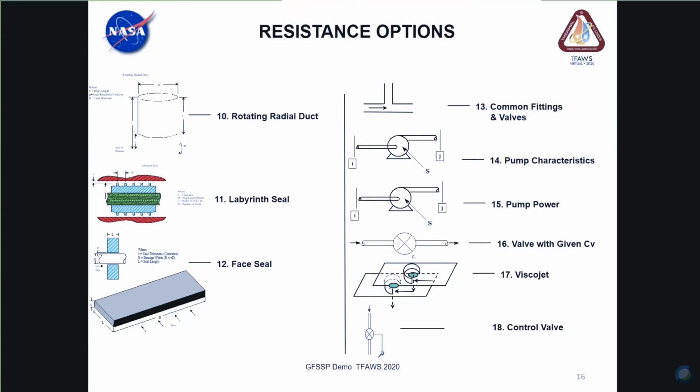Okay, on a somewhat related question. So let's say I wanted to model a fluid system that has a node that might, like in a ramjet, you'd have a shock train that would provide some compression, and you'd have a model of what the inlet and outlet conditions are. But that could change in length or shift within the system. Is it possible to make segment lengths adjust in time? Yes, it is possible to do that. You would have to write a user subroutine though, and change the properties of the segments with time.